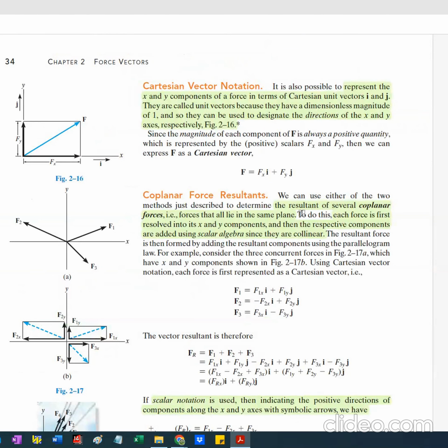Anyway, that's one way you report the x and y components, as separate values, but you can also include them into this vector format. So you calculate the way shown, with the angle or the little slope triangle, Fx and Fy, and then you state this vector equation. So you multiply the magnitudes of the projection x and y with their signs, negative or positive, with the unit vector.